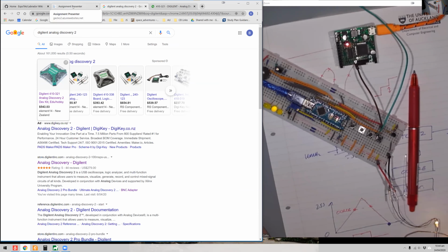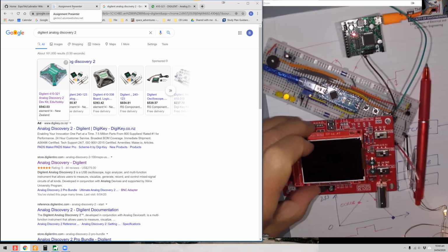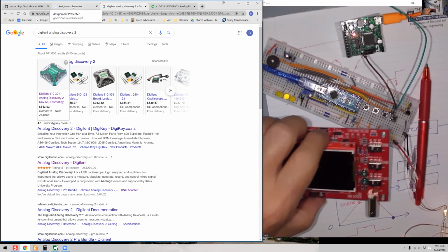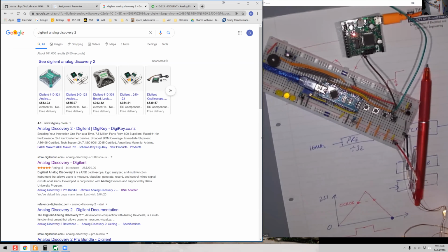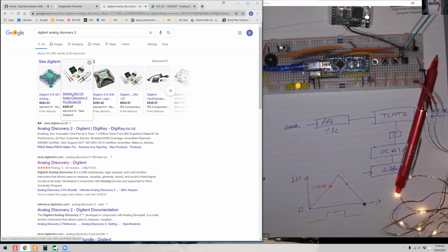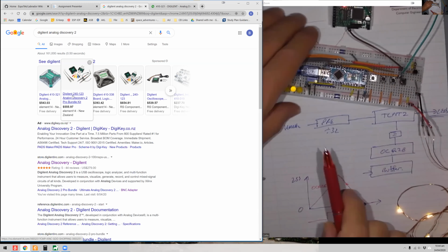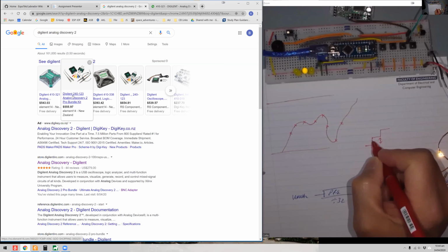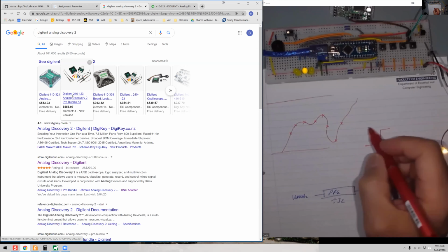And of course, there's plenty of other oscilloscopes you can have a play with as well. You know, I've got these little cheap hardware ones. This is not a bad one. And all these pulse width waveforms you can see on these scopes. Okay, I've got that one. I've got another couple up my sleeve as well, and they're all really useful, but they all have limitations based upon, and of course, what is it? It's the digitization, right, of this. So the resolution and the sampling rate.